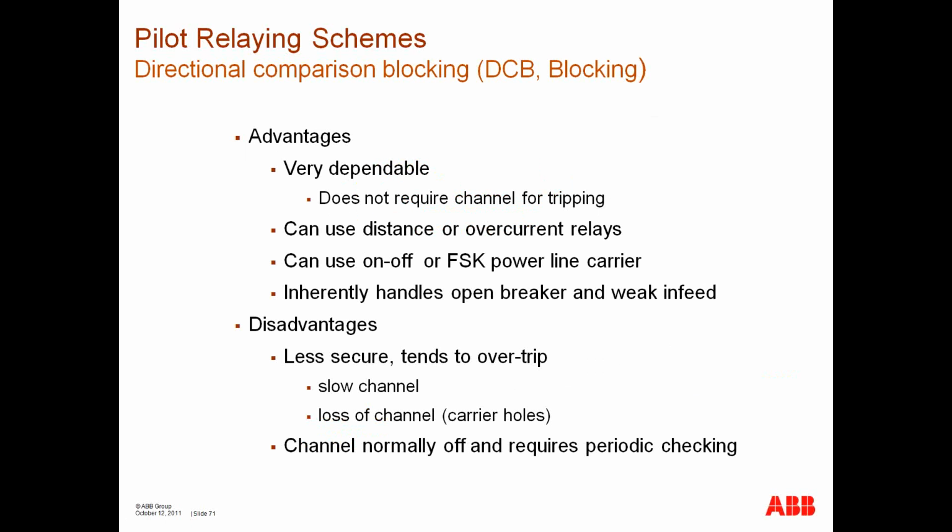Blocking systems are very dependable, do not require a channel for tripping, can use distance or overcurrent relays, can use on-off or FSK power line carrier, and inherently handle open breaker and weak in-feed conditions. Disadvantages: it's less secure. It may have a tendency to overtrip.